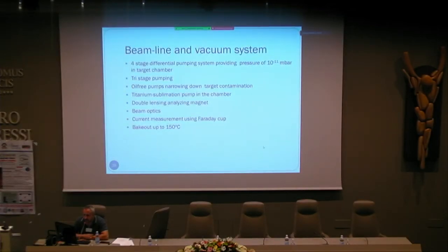Yeah, and as I said, the vacuum system is also state-of-the-art. We have a 4-stage differential pumping system that allows us, after heating up the system for 48 hours and cooling down with liquid nitrogen, we also have a titanium pump and an ion pump, so basically all the best things you can get for a vacuum system to get as low as possible.